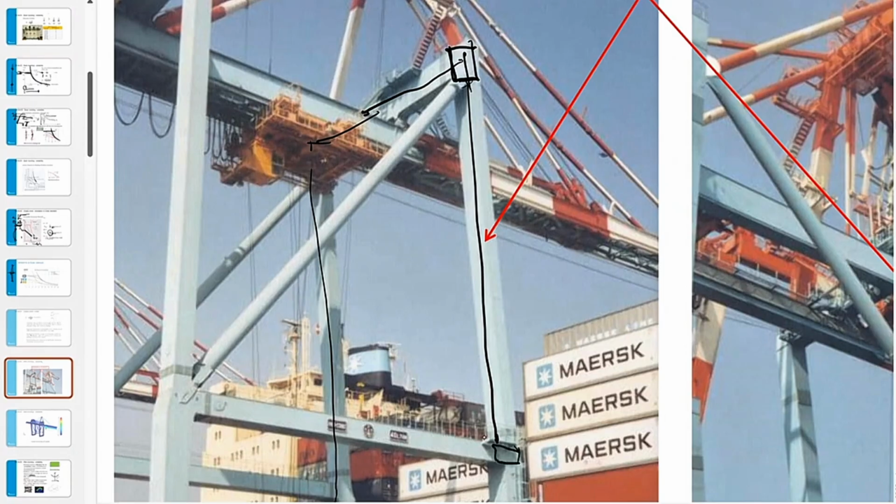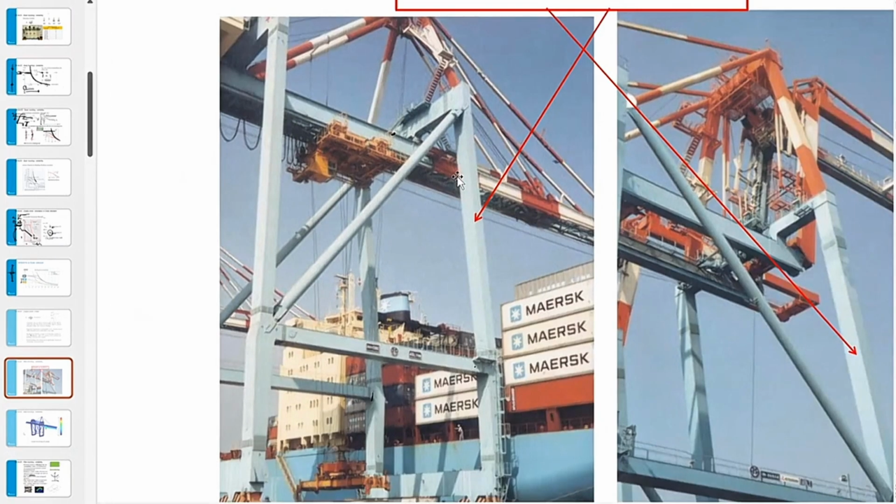So you could reduce the buckling length, instead of from center point to center point, you could do a small modification, but by default that is not taken into account. And especially in the design phase, I would not advise you to do so. It is slightly conservative, but you might need that extra limit later on in your design.